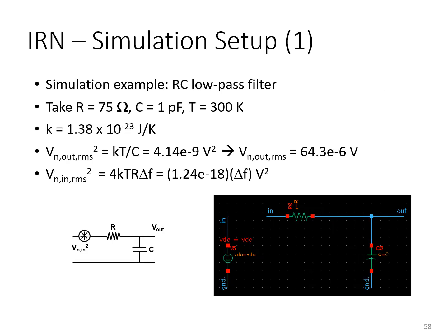So a classic example is to consider an RC circuit. If we think about an input voltage source Vs connected to a simple RC circuit, only the resistor here has any thermal noise, and it's modeled by the white power spectral density Vn,in that has a power spectral density of 4kTR.